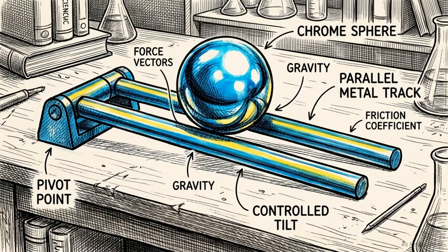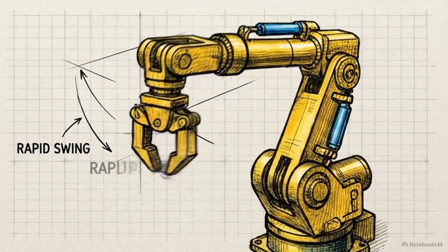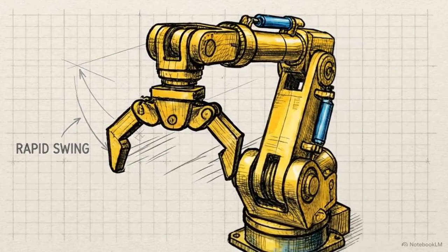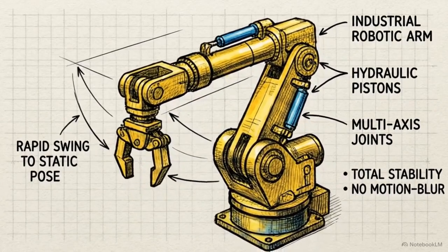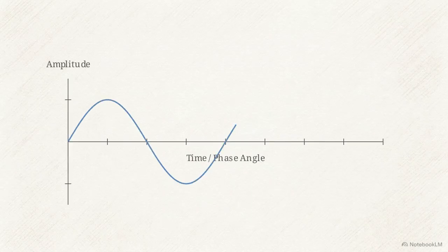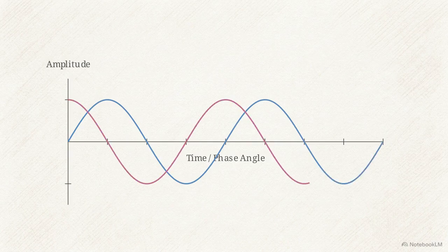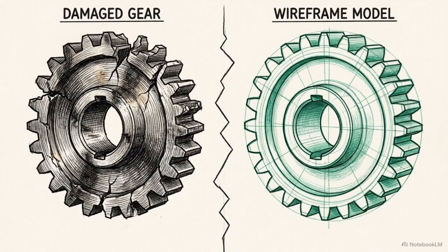The ball and beam mechanism is an academic apparatus, but the engineering protocol it requires applies to any complex automated system where precision is mandatory. Model-based software development enables this level of industrial performance. Simulating the plant dynamics in MATLAB allows engineers to expose hidden mathematical flaws, like a 270-degree phase lag, long before deploying logic to a real-time hardware controller. Moving away from hardware-first trial and error reduces the risk of mechanical damage and improves development efficiency.